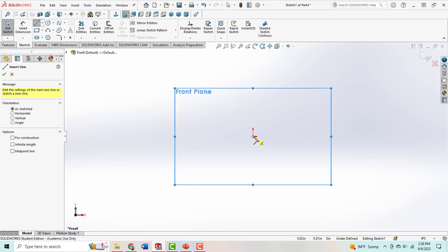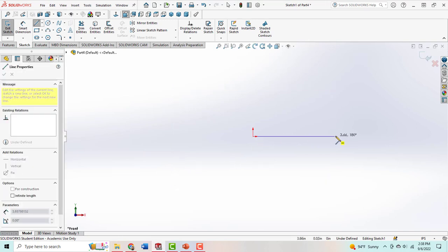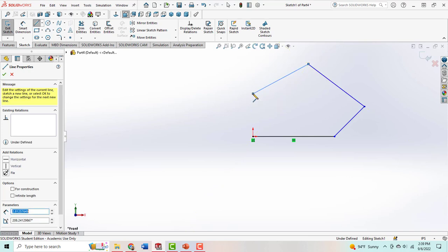I'm going to start by placing my first endpoint on that origin and kind of just drawing my line straight. And we have an angle this way, we kind of have this one going up. You can see in the assignment that we do want a perpendicular relationship for these two angles. So if I hit this guide mark, it's going to automatically put it in. I'm going to stay off of it just so we can kind of practice adding in angles ourselves. We have another angle over here. I will line it up with that vertical guide line and then straight back to the origin.